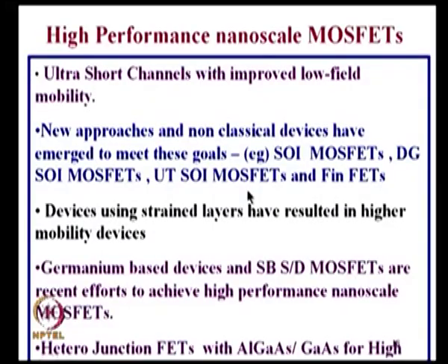So, if I stretch it, the electron has to jump on a longer path. That means the whole movement will be more difficult if I stretch it. So, what we said is the electron mobility increases if I use tensile stress, but because of that the hole movement becomes difficult, hole mobility becomes less if I stretch it.